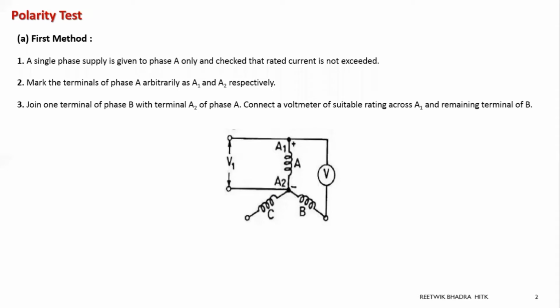We had seen that if there was a difference in polarity, the voltage would have been unbalanced, and there is another problem also. You please go through that. So it is very important, if it is a three-phase machine, that the polarity test should be done. Otherwise it may lead to unbalanced voltage. Some circulating current will flow, and many problems will come. So in the three-phase induction motor also, we have to go for this polarity test.